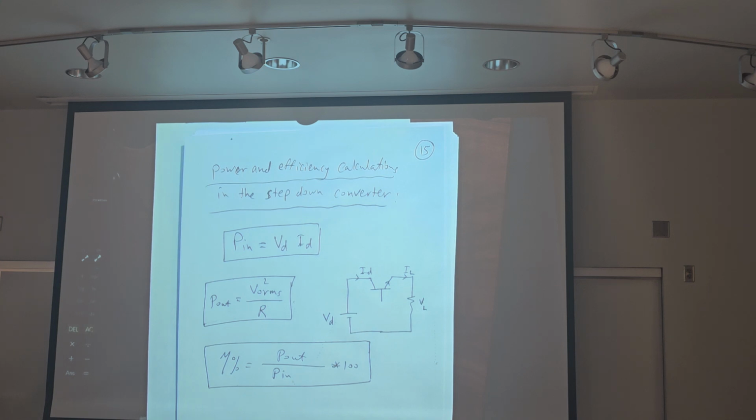Okay, with DC that's okay, but the efficiency depends on the RMS. The output depends on the RMS, not on the DC. Therefore, we calculated or tabulated V out RMS in the formula sheet with the equations required.